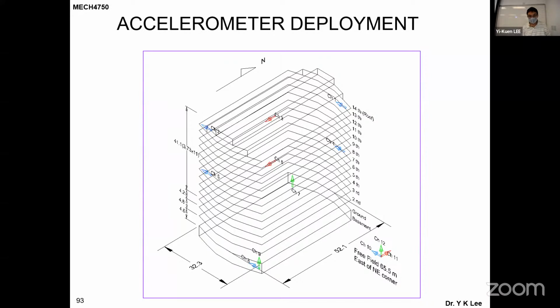And then of course they also mount accelerometers to what? Because they can do some modeling using commercial FEM software, but sometimes you still need measurement results, first for validation of your model. Second, you may also use your sensors to determine some unknown parameters like damping.